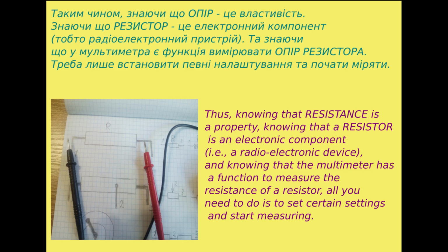But if you try to measure the resistance of a component inside some circuit, some device, the results can be wrong, because when the elements inside the device are combined with each other, they change their parameters. They work together. For that we make devices. So if you need to measure something, you should either separate it or be very careful, and before you do something, try to understand how it works.